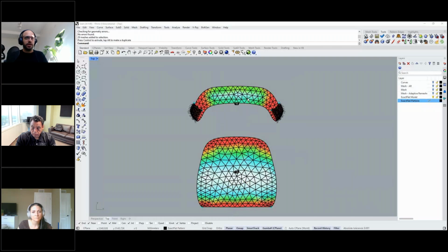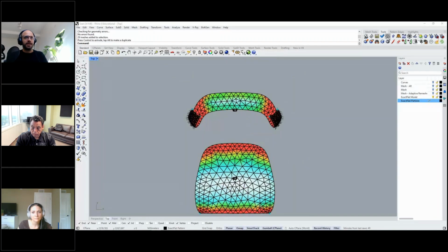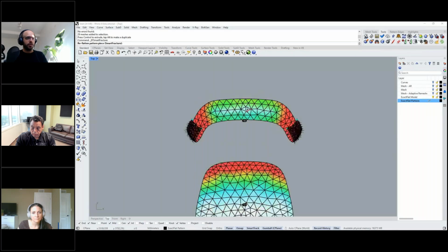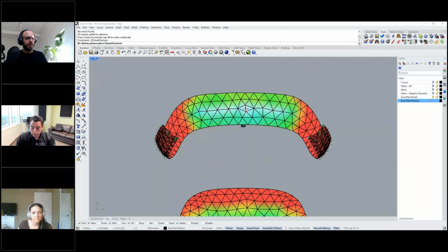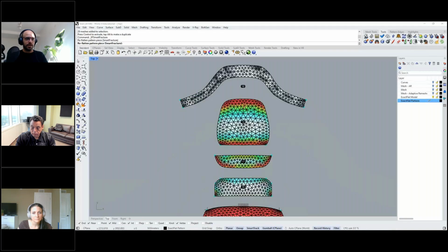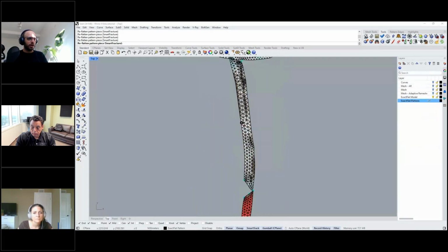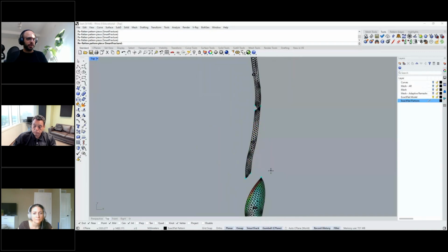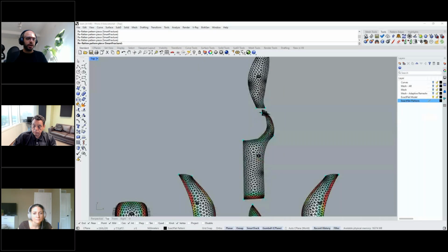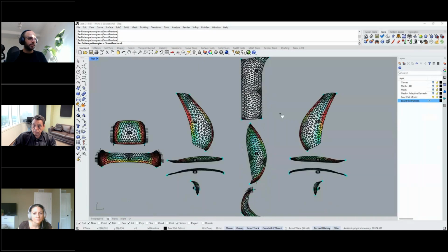So in order to do that, we can run the ExactFlat pre-flattener tools. So I'm going to select the Smart Fracture command. This command will extend my pieces on the ground or on the table. This will still not give me my final production-ready patterns yet, but it will prepare my flat patterns for the optimization process that will come afterwards.